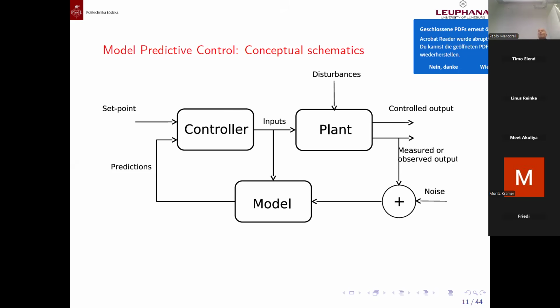Could have the presence of noise, but this is just a technical aspect. Using the states, I can predict, and the controller is exactly what I told you before. Basically, it consists of the optimizer and consists of constraints. In any case, here inside, you can imagine you have the vector of the error. We will see with MATLAB very well, and the controller generates an optimal input or inputs.